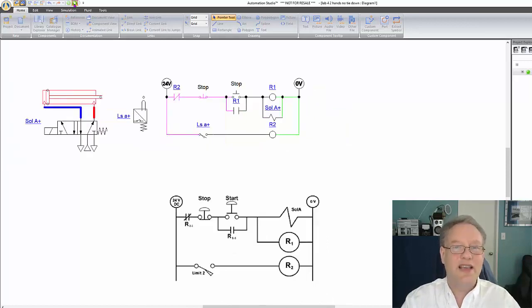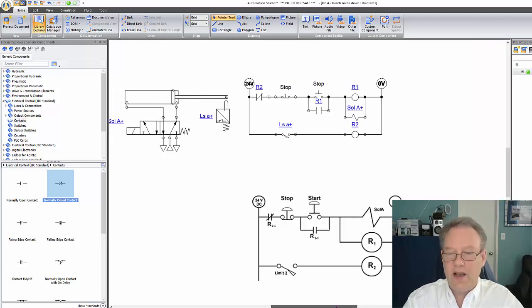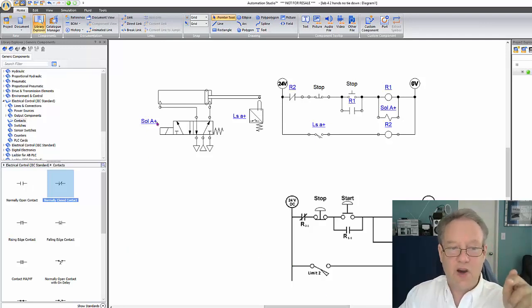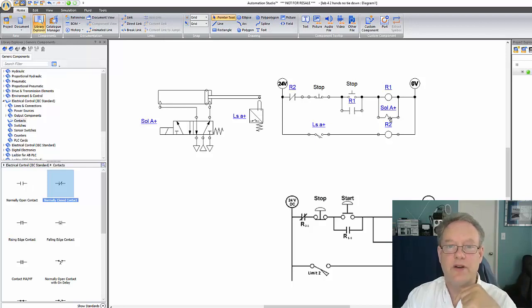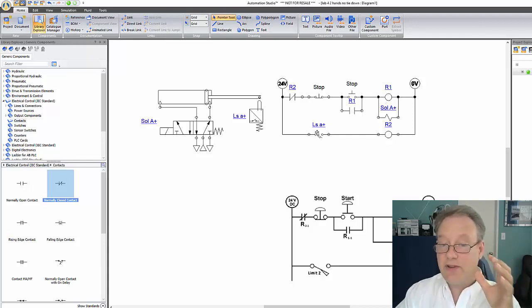We know how to associate two of them together. And you have to have two of the components in the diagram to associate them. For instance, this had a question mark in it before. I was not able to name that until I put this solenoid here. I'm not able to put relay contacts in here unless I had a coil in. So also this guy, I'm not able to put this guy in unless this is here.